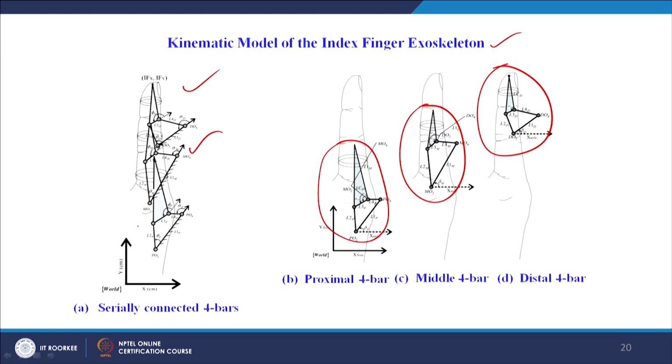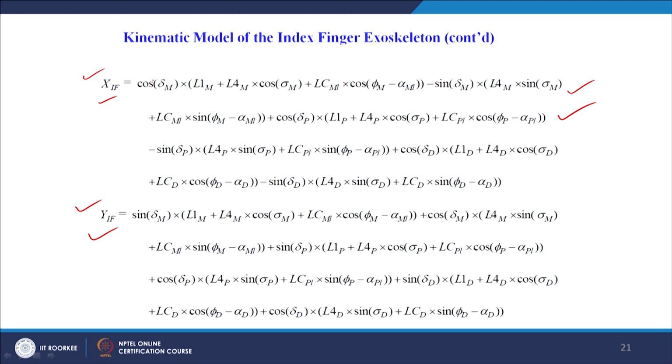That is, starting from this point we are able to reach here and then go here, then from there you reach here, then from there you can go here, then reach here, then reach here, then reach the tip. That is, from the closed loop equation method we are able to reach from the start point O2 till the tip position by this forward kinematic equation.